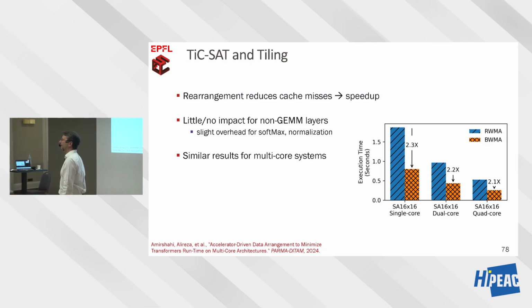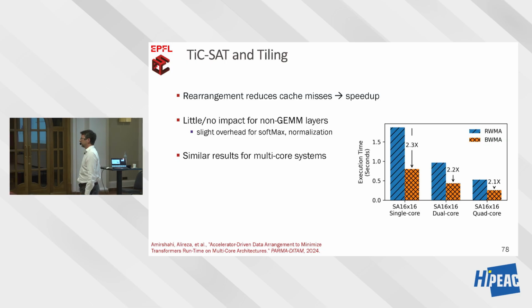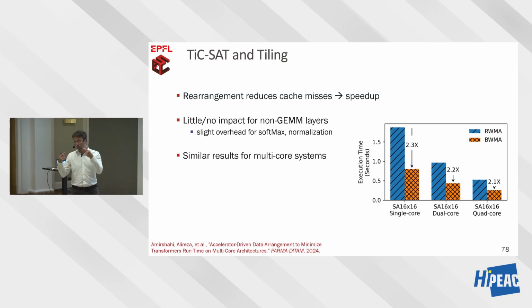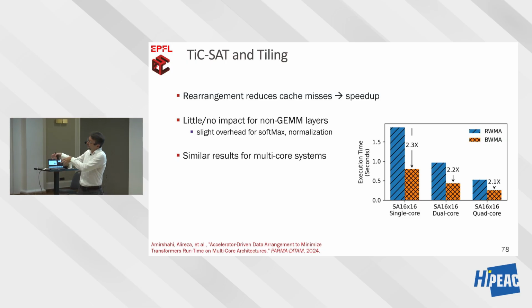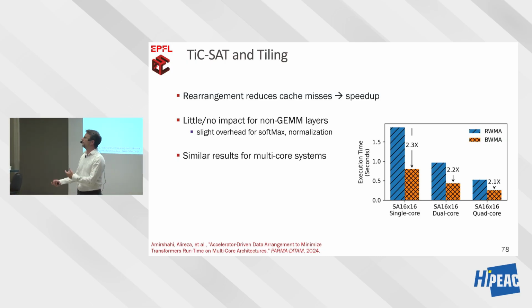Yes? Okay, the accelerator starts bringing in a new tile while it's computing on the tile that is already in the accelerator. By itself, the accelerator could start programming weights as the previous stripe is finishing, but the processor pipeline doesn't have the bandwidth to do that. So you have to decide which data you want to transfer in and out. You may think about different styles of integration, which would allow you to do that. I will briefly mention that in the next slides.